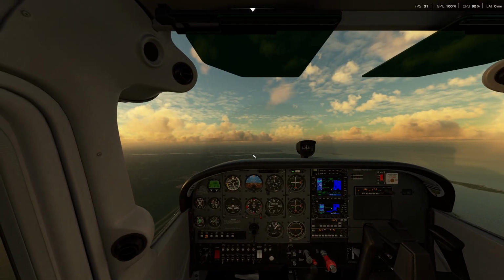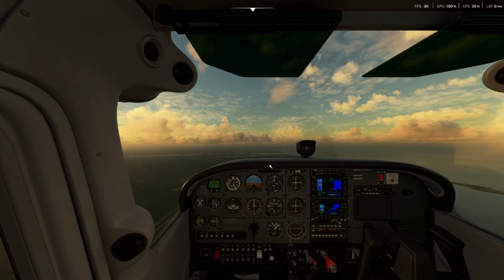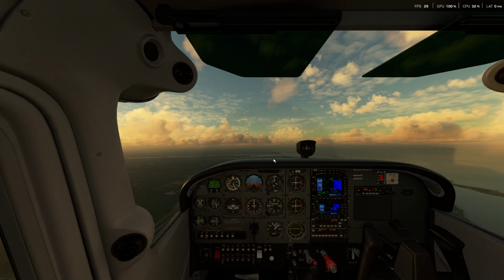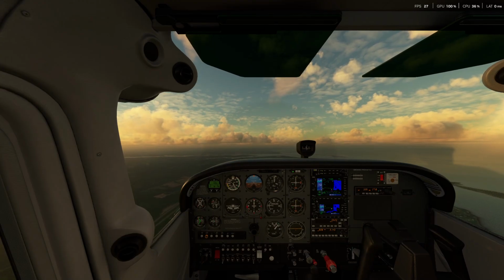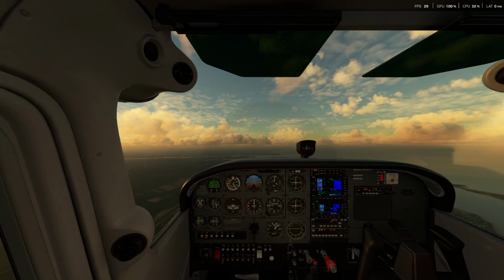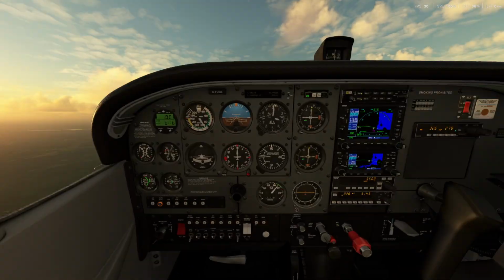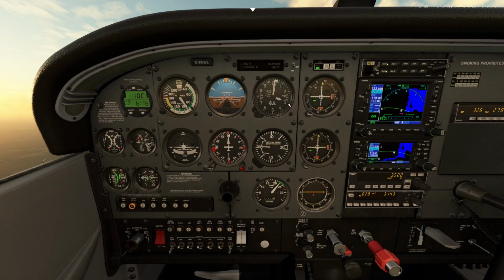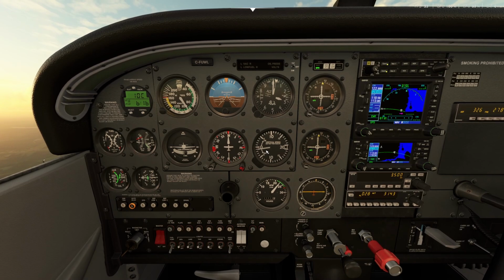The indications in the cockpit, you can see. Now you are a VFR pilot, so you're not technically supposed to be looking a great deal of time at your instruments in the cockpit. But you can take quick looks at your altitude and see that it's not increasing or decreasing at all. Vertical speed down here fluctuates a little bit because it's not trimmed perfectly, but you can see that you're not increasing or decreasing the rate of climb or descent.